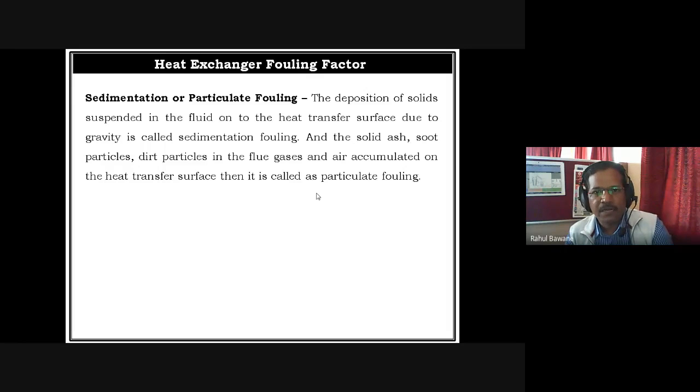So the carbon layers form a barrier to the mesh particles inside the silencer, so it can't arrest your smoke particles or sedimentations. It will form a carbon layer, and it will behave like a barrier for heat transfer also. Such a kind of layer formation, that black smoke formation, is known as particulate fouling.